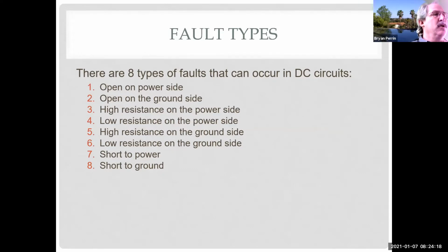We're going to diagnose an open circuit, a short circuit, because we know because of Ohm's law and a series circuit, if I have an open anywhere, the circuit doesn't work. So the fault's the same, whether it's on the power or the ground. The location of the fault changes, but the actual fault is still an open circuit.